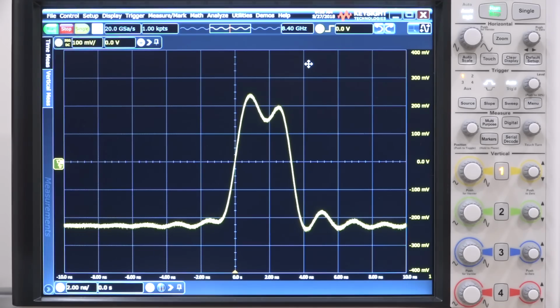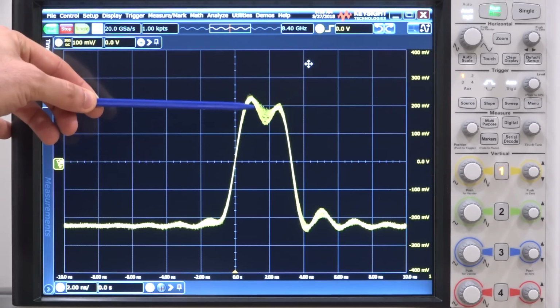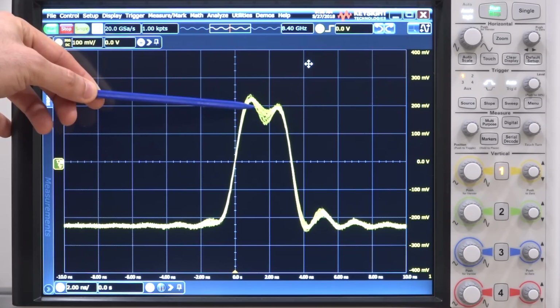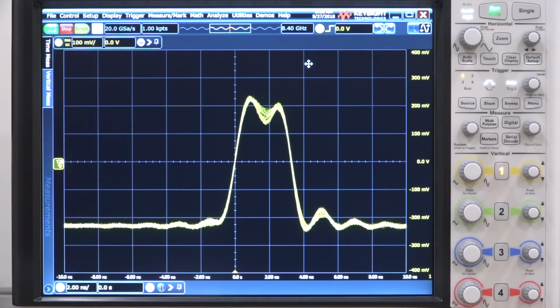Now, I can get rid of this by playing around with the settings and even just updating the settings of the other channel, meaning that this is definitely a data generation issue internally that can be fixed in firmware. One of the other reasons it happens is because the frequency I'm generating, 10 megahertz, is a multiple of the clock frequency of the DAC itself. So if I go to 11 megahertz, for example, you can see that region is no longer changing slowly. It's changing so fast that we're getting superimposed waveforms, so it becomes just a fuzzy amplitude jitter there. So if I go back to 10 meg, you can see it again.